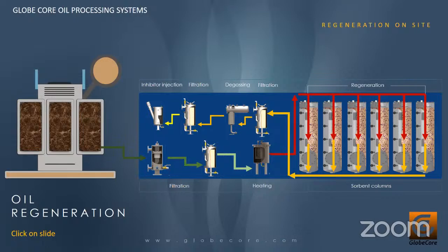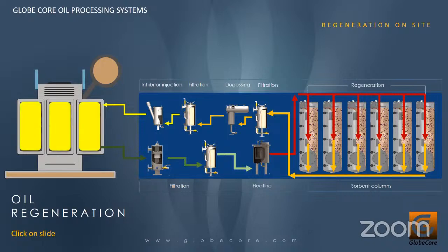As we said before, according to the local standards, the oil should contain the inhibitor at approximately between 0.2 and 0.3% of the total volume of the oil. And after that, after inhibition, the oil is supplied to the transformer. So we can see the transformer now looks like new. We have removed the contaminants and sludges from the bottom of the transformer. We have cleaned and flushed the core of the transformer and removed all the contaminants from the paper insulation. And what is the most important, we removed the moisture from the paper insulation of the transformer.